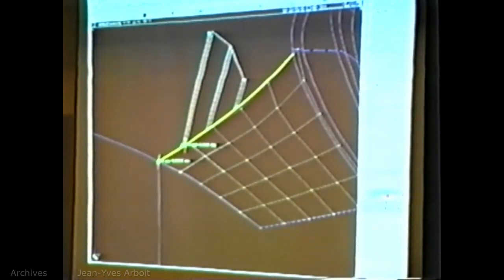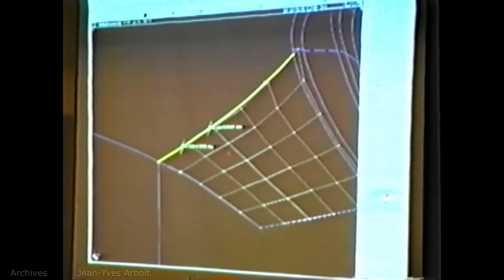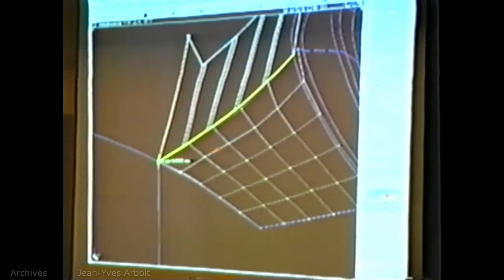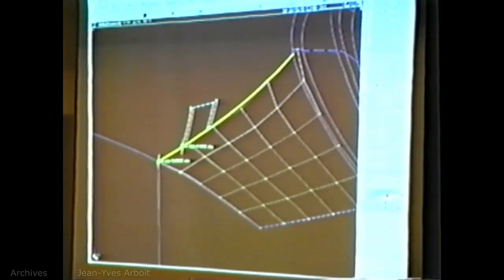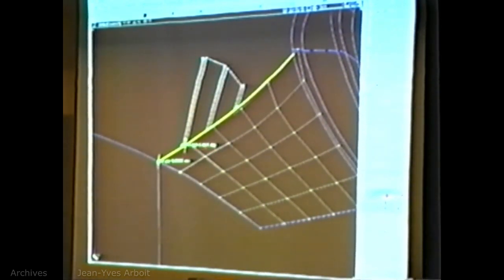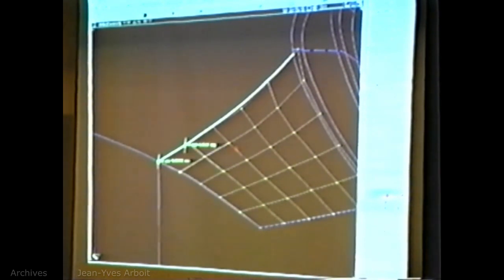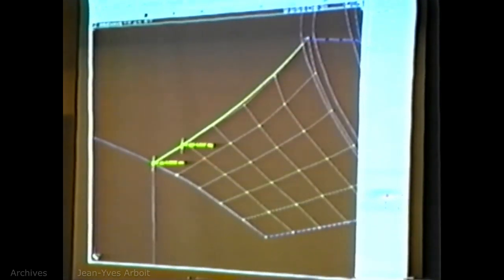So that's sort of jumping all over the place. That's a good time to turn on the step size. And then I can just make very small incremental movements. Basically make a modification. In fact, I can use the arrow keys, and again, those are using the values that are put into the step size. And turn the whole hull there. Also, if I make modification to that again,